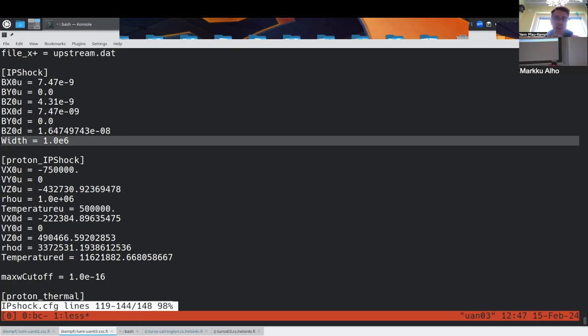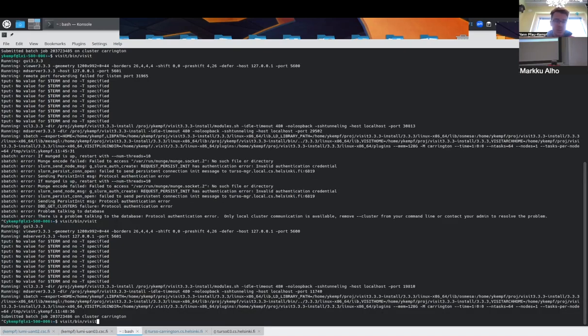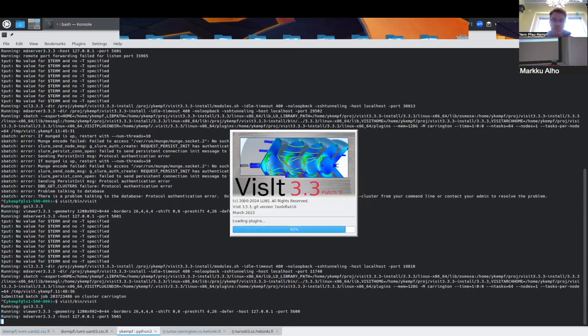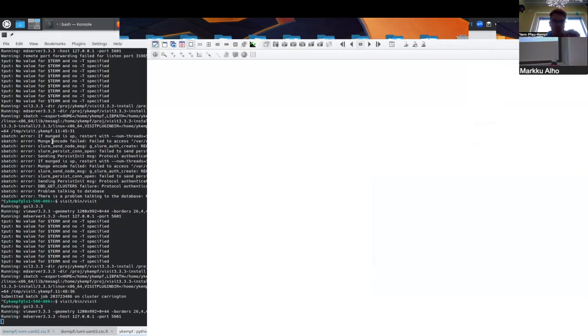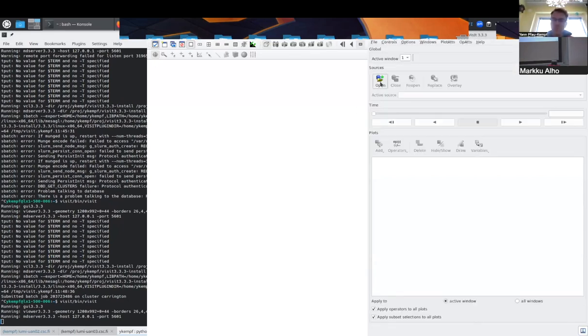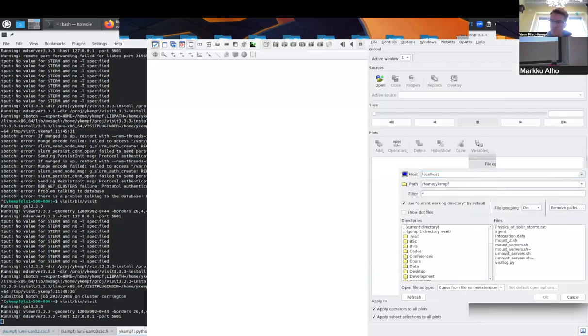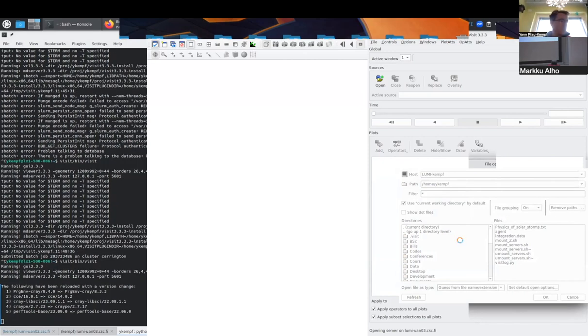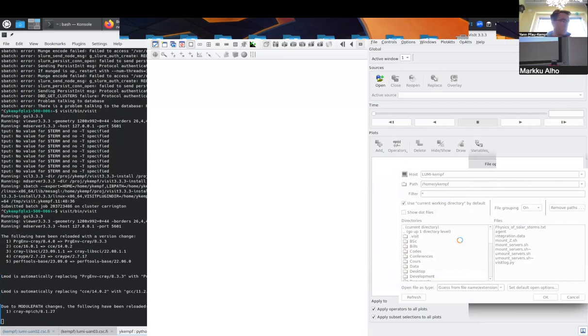So one of the reasons we don't want to have a Rankine-Hugoniot solver in the code itself is that, as I alluded to previously, Rankine-Hugoniot conditions are evaluated using MHD, and we are simulating kinetic physics. So the energy balance at the shock in a kinetic shock simulation is not the same as the MHD approximation.